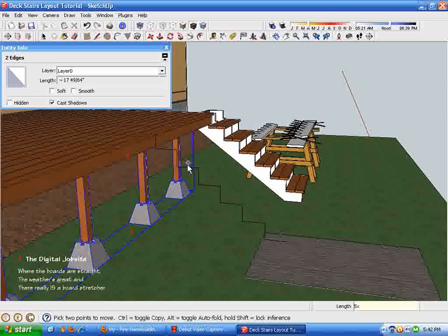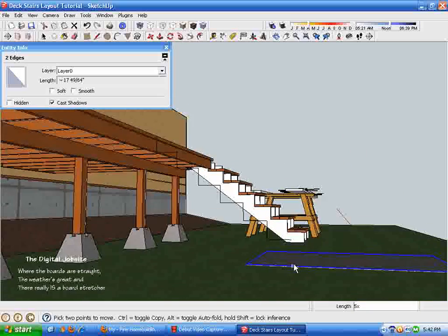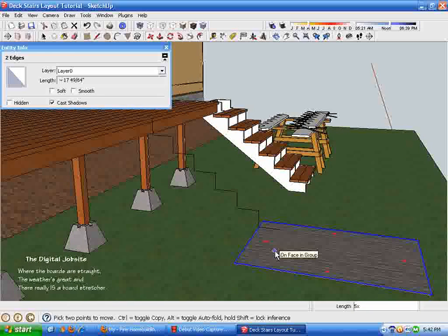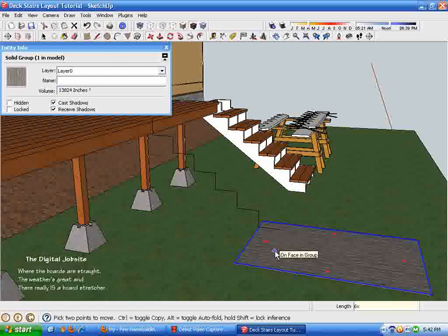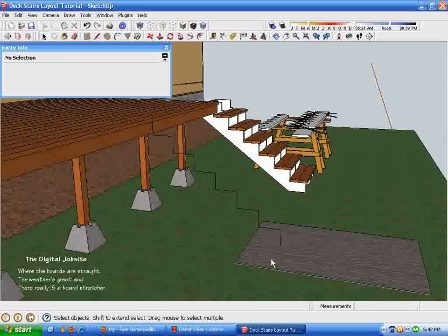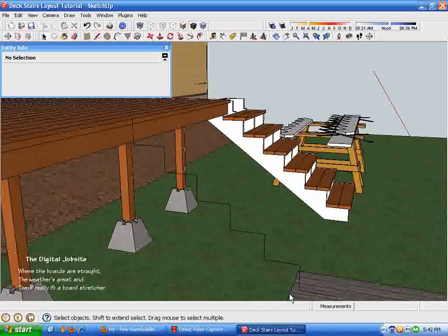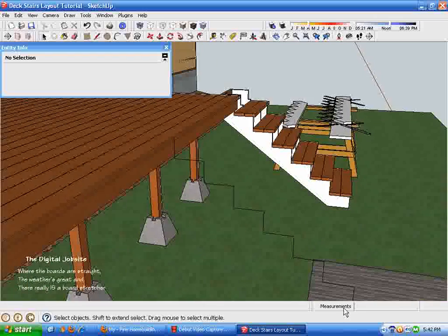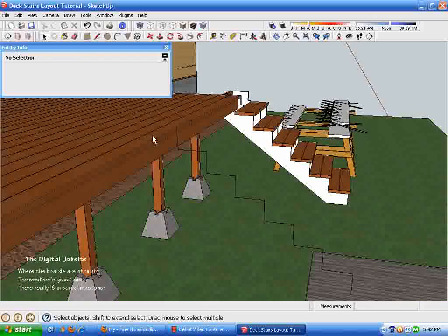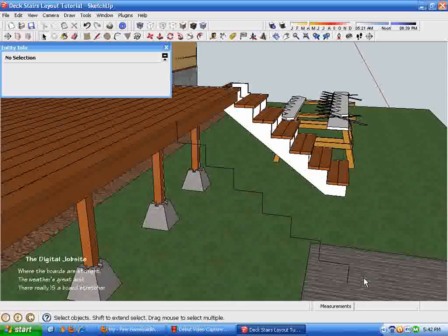And it's not quite far enough, so what I needed to do is overwrite that with 6x, enter, and that adds one more step to my little line there. So what that line represents is the individual rises and runs that it would take to get from this deck level to that concrete slab level in equal increments.